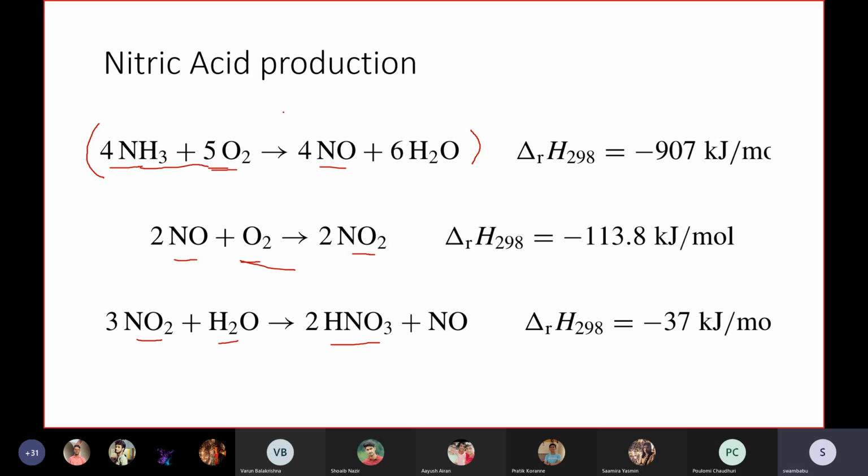So we don't have much problem with pressures. We don't need any high pressures. If there were reversible reactions, to push the forward reaction better, we would need high pressure. So we don't need high pressures here, unless the catalytic reaction requires high pressure. So these are simple reactions.